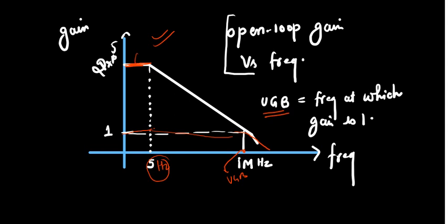So for the open loop configuration, you will see that this is gain and this is your bandwidth. If you want a lesser amount of gain, then your frequency response would become something like this, right? Up to 1 megahertz, it will give you a gain of 1, right? So this is what we do with the feedback. We are decreasing the gain and we are increasing the bandwidth.